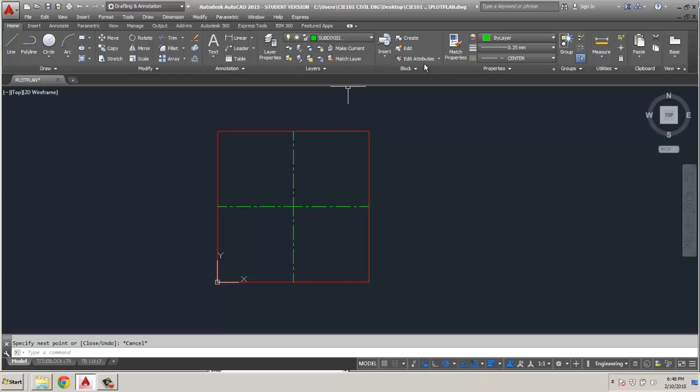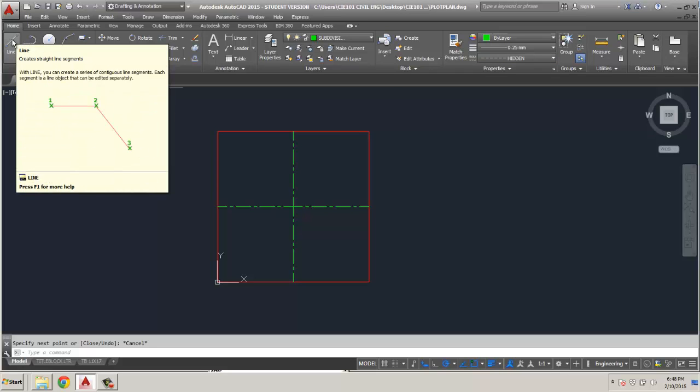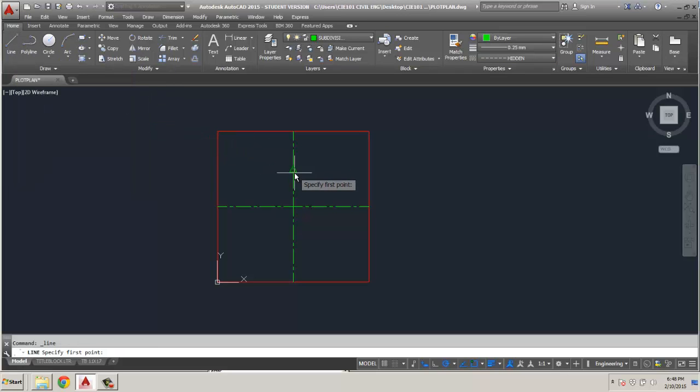So now we're going to change to our hidden line. We're still in the line type scale at 5,000, which is fine. We're going to put a horizontal line right across here. Hit enter. We're going to do a vertical line straight down. Hit enter. We're going to do a vertical line straight down here. Enter, enter, and another one, subdividing it this way.